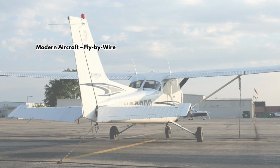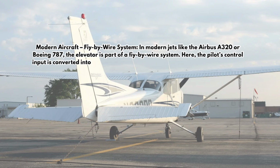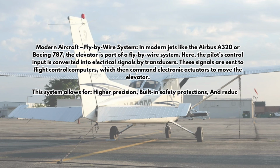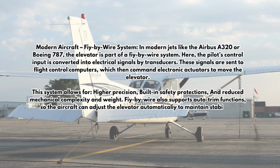Modern aircraft, fly-by-wire system. In modern jets like the Airbus A320 or Boeing 787, the elevator is part of a fly-by-wire system. Here, the pilot's control input is converted into electrical signals by transducers. These signals are sent to flight control computers, which then command electronic actuators to move the elevator. This system allows for higher precision, built-in safety protections, and reduced mechanical complexity and weight. Fly-by-wire also supports auto-trim functions, so the aircraft can adjust the elevator automatically to maintain stability.